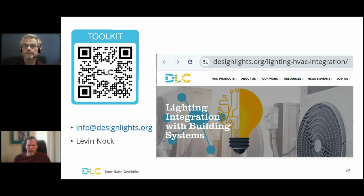Yeah, I can add a little bit to that. The more data you have, there's more things you can do with it. Levin, you mentioned one of them, which is density. How many people are in a particular zone? Sometimes you can't do that with one sensor, but if they're spread around and you can average or accumulate those, density is a very good metric to use on the HVAC side because you can adjust your airflow based upon the number of bodies in the room.